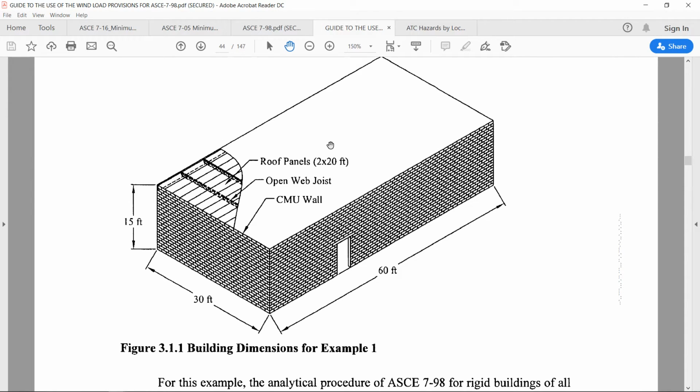And if a positive pressure is developed inside the building, that positive pressure will be exerted on all the walls and roof from inside. So that means that positive pressure will create pressure on all the walls and roof from inside to outside. But suppose the wind is flowing like this and there is no opening on this side, and the wind passes over the building, then on the leeward side there will be negative pressure. And if the building has openings on the leeward side, what will happen? It will extract air outside, and that will cause a negative internal pressure. So in that case, this negative internal pressure will be acting from outside to inside.